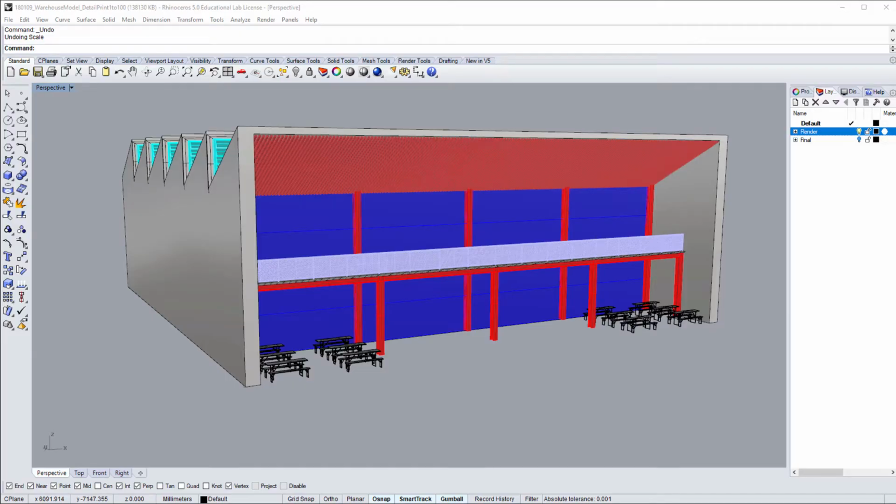In many instances, some parts of your model will need to be modified to ensure a successful 3D print. In this video, we'll look at how to deal with modifying detail in your model and discuss different techniques to enable it to be 3D printed successfully. There's three ways to approach modifying thin or detailed elements of your model. Elements could be thickened or simplified to meet the minimum size requirements, turned into a fine surface detail on a thicker base surface, or removed entirely from the model.